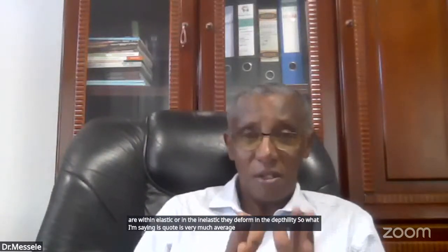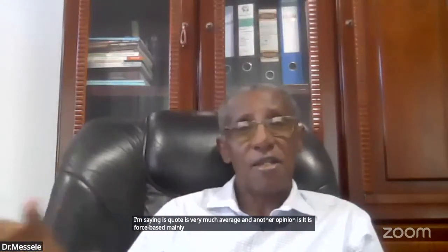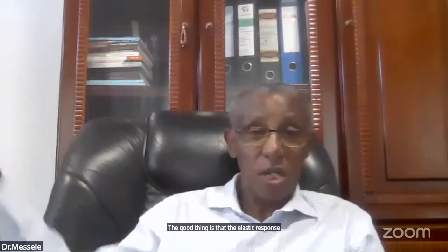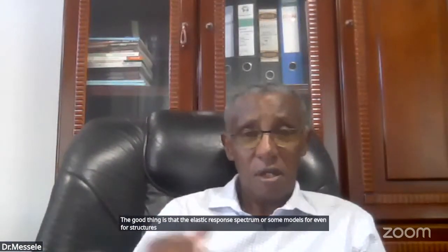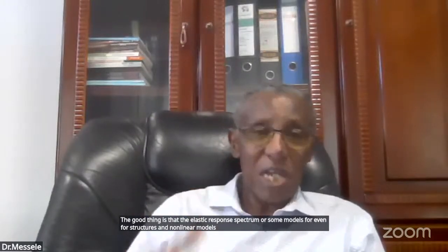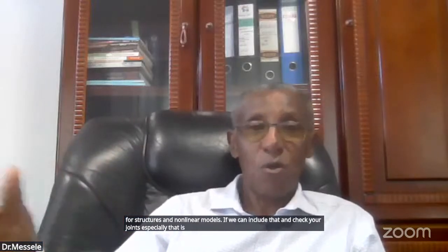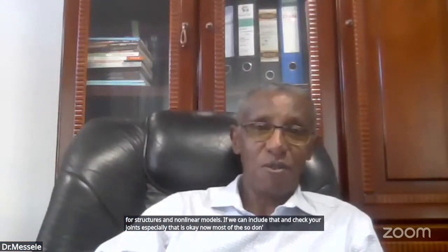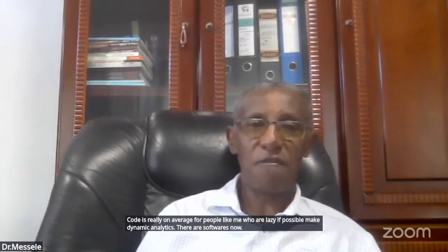Another opinion is that it is mainly force-based. The good thing is the elastic response spectrum, or some models, even nonlinear models for structures, if we can include that and check your joints especially, that is good. So don't be comfortable with the current code either. The code is really an average, for people like me who are lazy. If possible, make a dynamic analysis. There is software now; it's not that difficult. We can catch different modes.